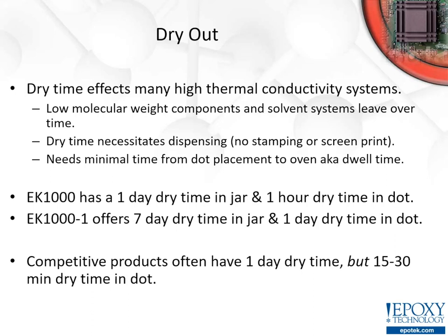If it exceeds that 15 minutes, the die doesn't actually wet into the silver fill system. You don't get a nice fillet and you don't get a good interface. The material becomes too hard and too high viscosity to the point where you actually get that trapped air and non-wetting effect that we discussed.